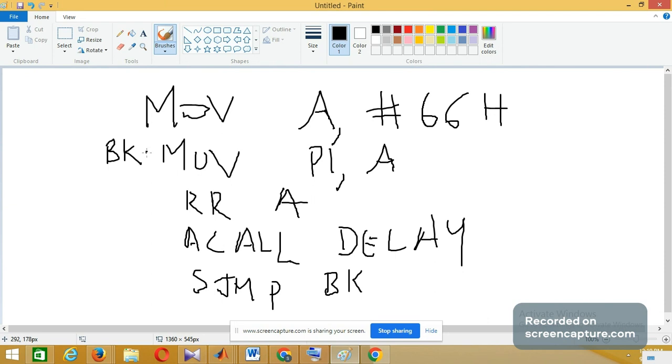Sending rotated value to P1 continuously. So this is the program to rotate. Now we have tried the delay subroutine. So the delay subroutine can be very simple. Use software delay. Don't use timer 0, timer 1 and so on.